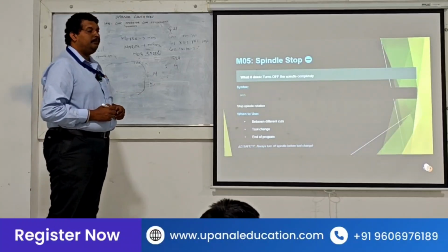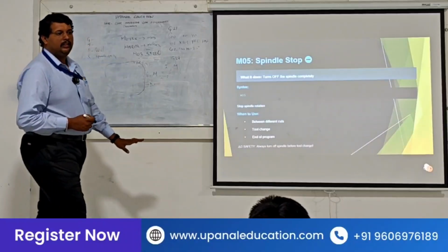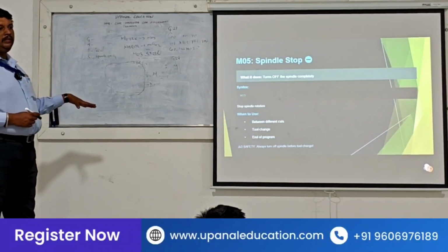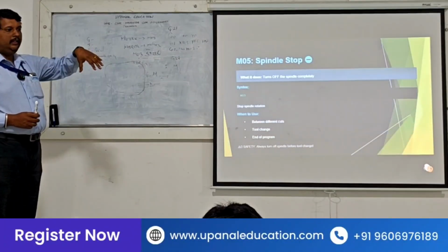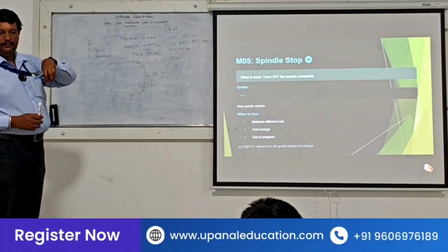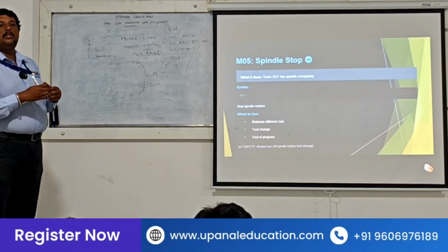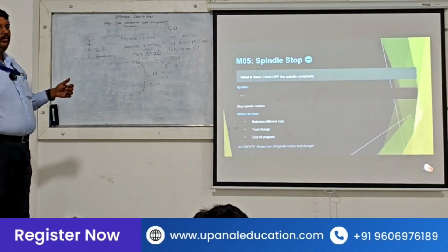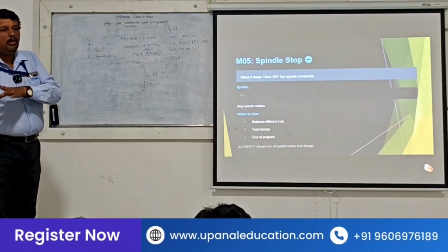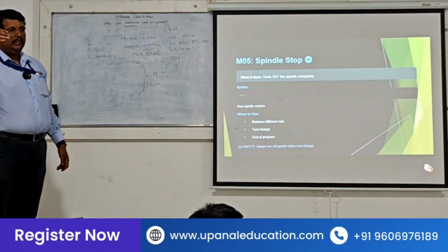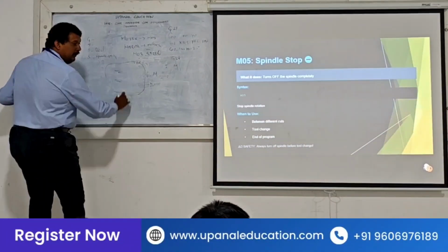The code is M05. This will be at the end of the program, once the work of that tool is over. It can also be in the middle of the program. How? If we use 2-3 cutters in one program, normally we use only one cutter. But when it is a long program, 20 or 24 hours, we can't stay near the machine. So what will we do? We will club all the programs together. Multiple tools programs put together, first program finishes, then the next program runs, completely.